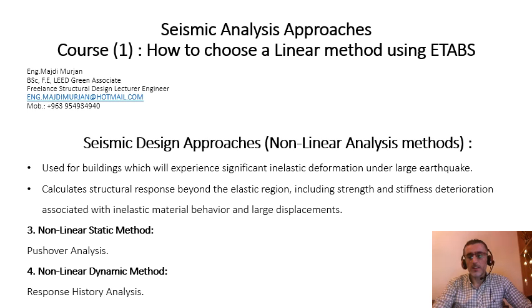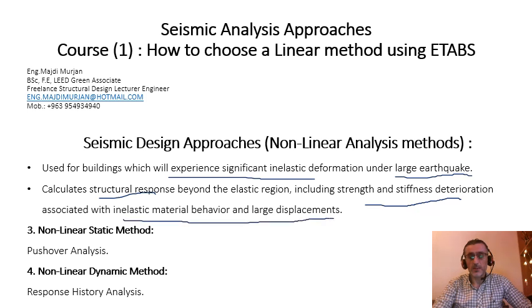For nonlinear analysis methods, they are used for buildings which will experience significant inelastic deformation under a large earthquake, and they calculate the structural response, strength and stiffness deterioration associated with the inelastic material behavior and large displacements. We will deal with it differently from the linear analysis methods. We have pushover analysis, the nonlinear static method, and we have the nonlinear dynamic method, response history analysis.